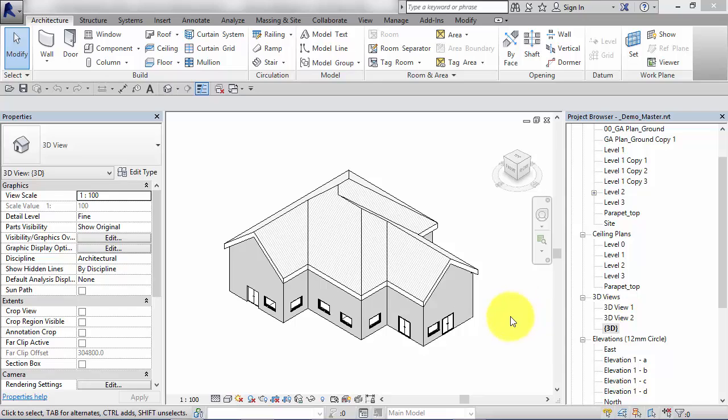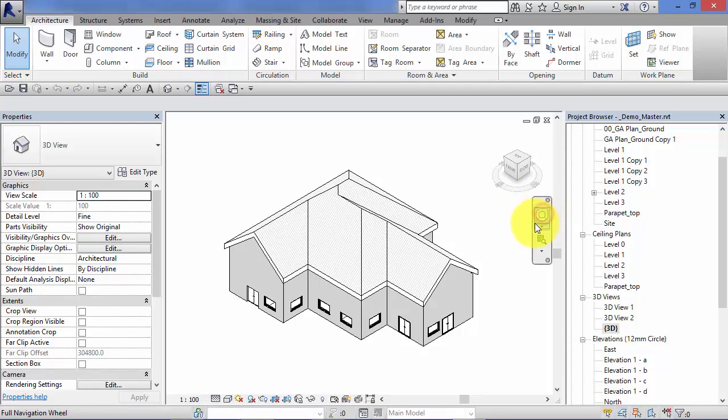In the last unit we saw how there was a steering wheel for 2D navigation. It's exactly the same in the 3D navigation, i.e. we have a steering wheel. So if we click the steering wheel icon in the navigation bar, out comes our 3D steering wheel. So a little more complex than the 2D one, some more options on here. So for the rest of the unit I will take you through how these various tools work. Just before I do so, just point out we've got the little X. Remember, that puts the steering wheel away. So let's bring it back out again.